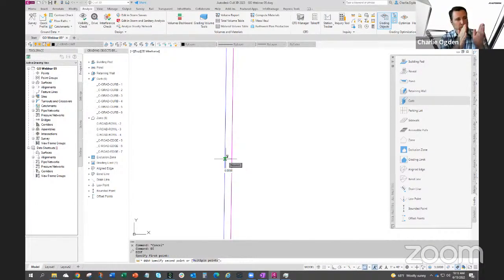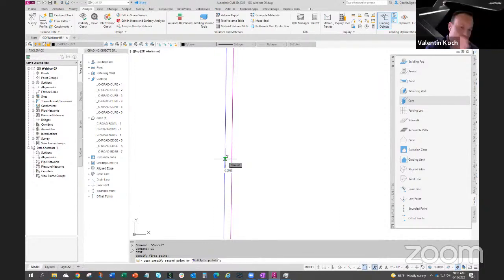That offset is 0.01, so I just picked halfway, somewhere right in the middle. Which is good because there we have no constraints. It's a wall and the drain line is right there, and the pavement doesn't touch the drain line. So we should get nice crowning that way.